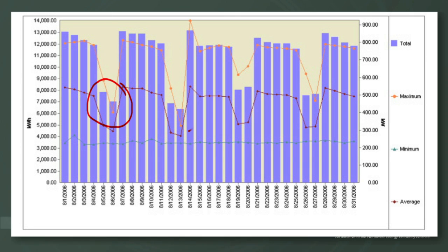So typically, Saturday has a higher peak usage than Sunday does, and also is using more kilowatt hours. In this case here, that's the same for both these weeks. Now this weekend here had a higher peak demand on Sunday and a lot more energy usage. This might key you in to look and try to find out what happened on those 2 days. Why are they not in the same pattern as the rest of them?